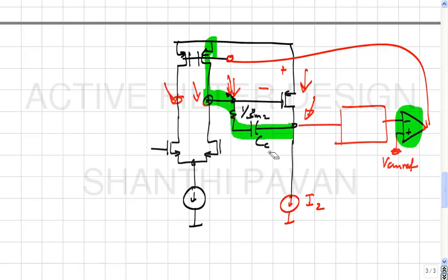Yes, yes. Okay. So, anyway, this kind of common mode control has several problems, which is why a lot of people do not use it. It is a subtle problem and it is not immediately obvious. People did start doing this, and then found that in some of their chips once in a while all the op-amps would simply latch up, and the only way to get them out of this kind of behavior was to turn off and turn on the supply.